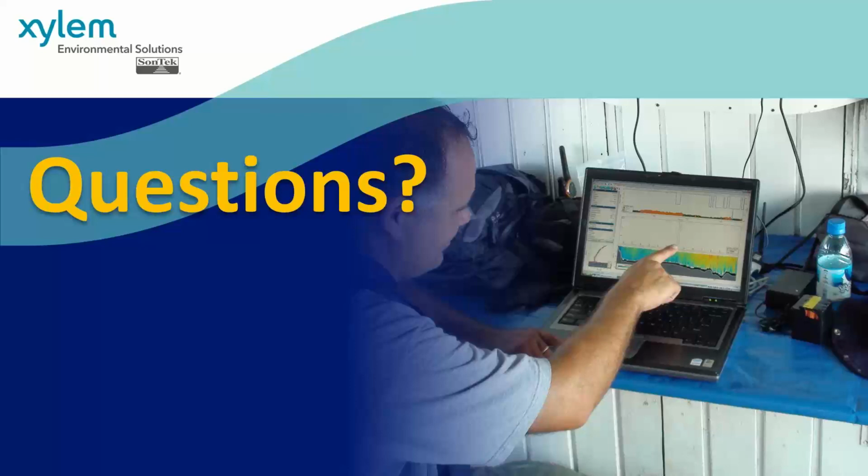This is site-specific, and we're still looking at the data. It's really showing that we need more than just a level during a flood event to get an accurate discharge measurement. But generally speaking, yes, you can do just water level measurements.